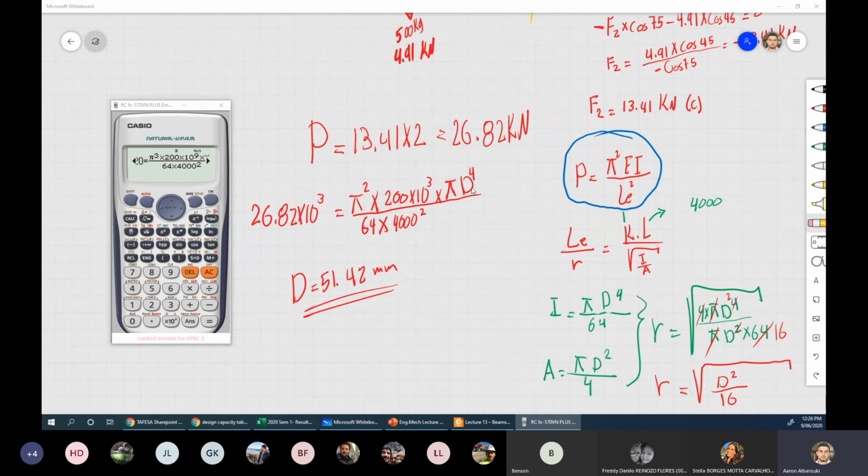And that's what I don't want to have. If we need our answer in millimeters, I have to use megapascal, because it's Newton per millimeter square, since my desirable answer is in millimeters. If you need your answer in meters, yep, go ahead and use kilopascals, for example, if you have kilonewtons there. That's what you're doing. 200 times 10 to the power of 9 will be in kilopascals rather than megapascals. Whereas we need our answer in millimeters, so the E value, the elastic modulus, should be in megapascal, so I can get my answer straight away in millimeters.